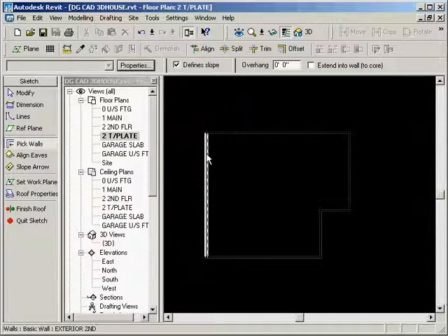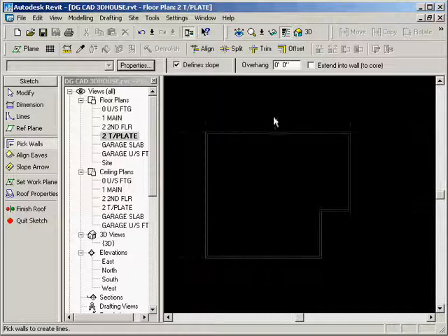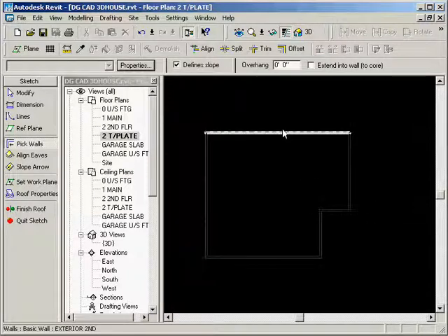And of course, we're into now sketch mode where your objects get grayed out. You can't edit them, and now you get into this unique form that Revit uses, where the lines are burgundy or maroon, and you sketch in a kind of a profile and turn it into the roof. And when you want to edit it, you come back and you click on it and you say edit sketch, and you come back into this mode.